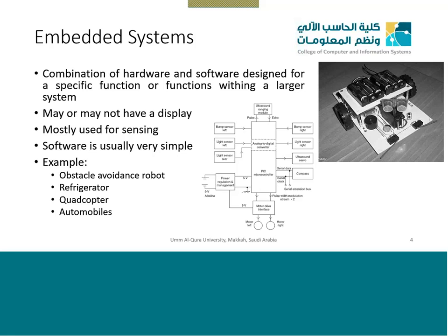So in that case, you need a very powerful system. But here we need a processor which is very simple, whose processing power is less, but which can do that specific task quite quickly. The RAM and the ROM will be very limited, and that is the heart of this system. Other than that, we need some inputs, like in case of your thermometer, it will be the temperature sensor.